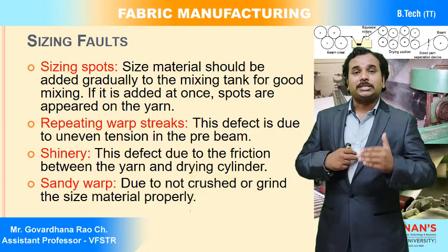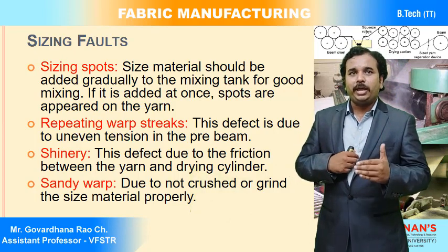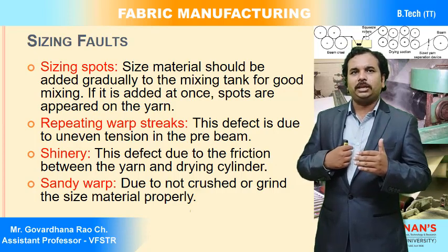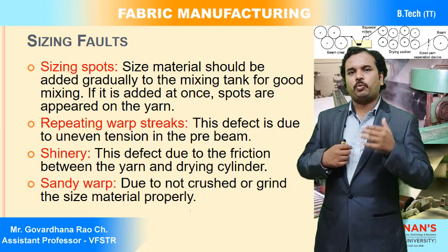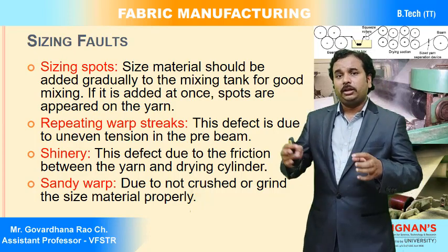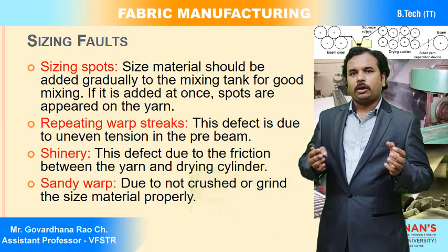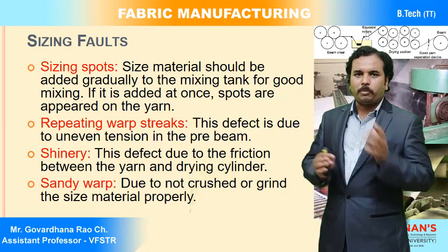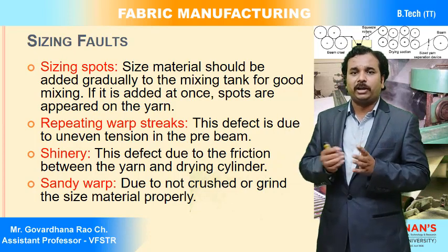Sizing spots. Size material should be added gradually to the mixing tank for good mixing. If it is added all at once, spots are going to appear. Generally, in the size box we should maintain the size paste level.